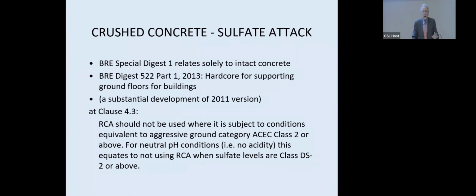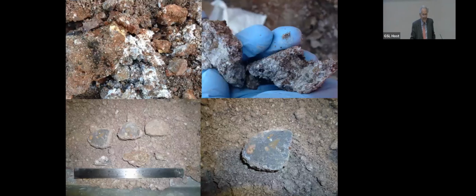Sulfate attack, well, there's now guidance on sulfate attack of crushed concrete. Basically, class 1 is the best. You won't get any better. And that's some bits of crushed concrete that have been in contact with sulfate, just lying on sulfate soil for about a year or two. Quite interesting, bottom right there, that's a bit of slag cement concrete, the blue color, and it's survived. The dust around was all lumps of concrete, but just sulfate. So we are, I think, at risk.